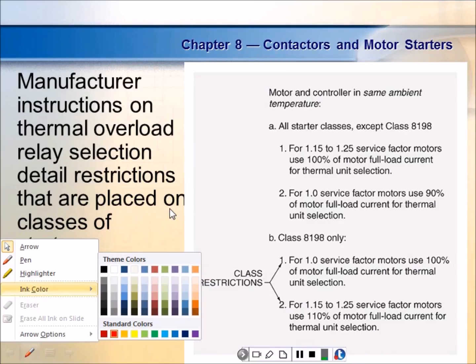Anything where the load varies. So you have a motor that's running a certain load, and then all of a sudden it's got to do 25 horsepower, and it's a 20 horsepower motor, but it's only got to do that for a short period of time. So it's out here running something, and something else needs to start, right? You understand? Okay. And we start this one, the motor is not going to pull its start current because it's already in motion, but it's going to pull more current until the device gets up to what? Gets up to speed. Does that make sense? Okay.